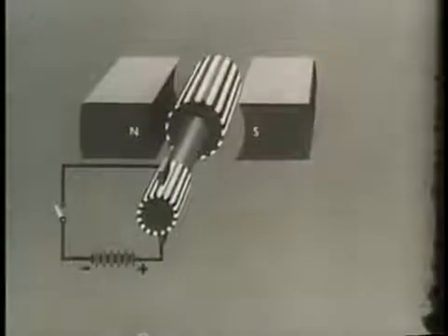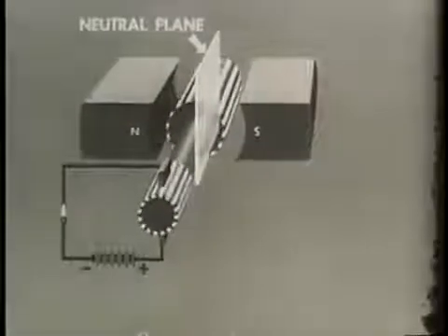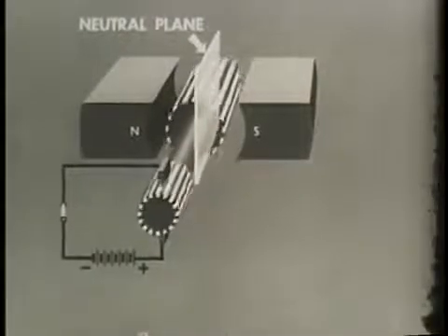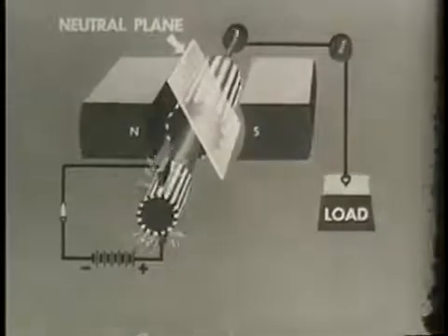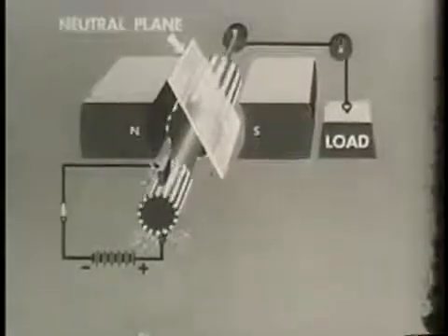Here in the motor, as in the DC generator, there is a neutral plane. The interaction of the conductor fields on the main field causes this neutral plane to shift and sparking to occur when a load is added. Sparking in DC motors also produces burned commutators and interference in nearby electronic equipment. This sparking can be prevented in one of two ways.